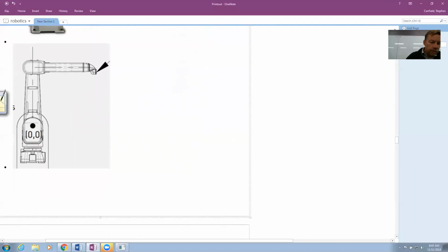So if we look at our joints, we got a joint 1 here, joint 2 there, joint 3 here, joint 4 there. Now this guy is going to seem strange. There's a revolute joint right here, so it runs this way. Joint 5, and then finally a joint down here, 6. So this guy is not a spherical wrist robot.